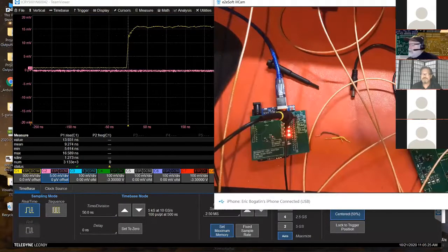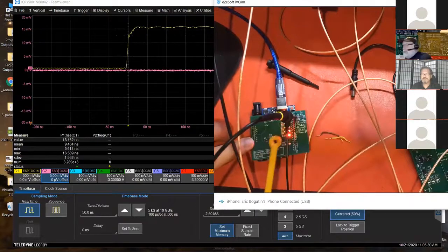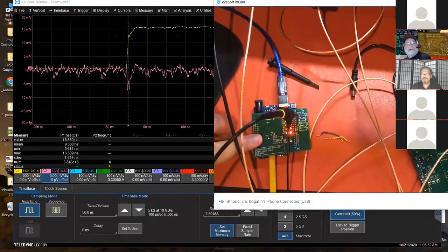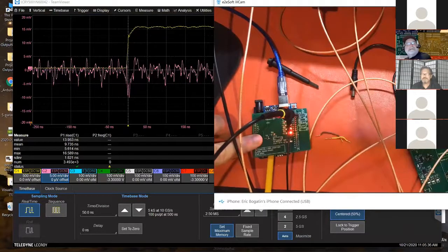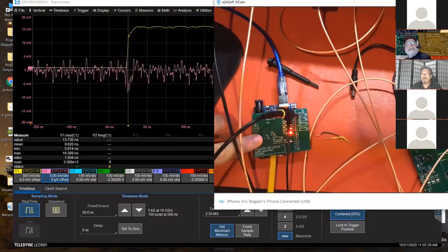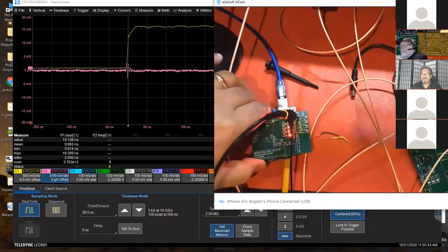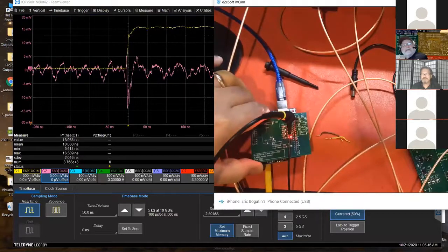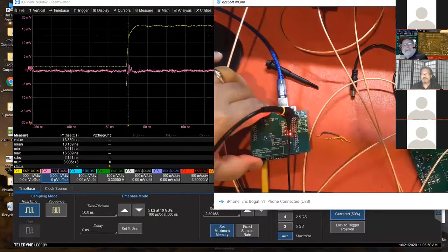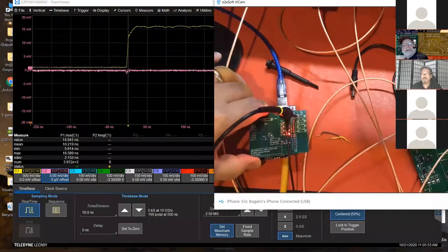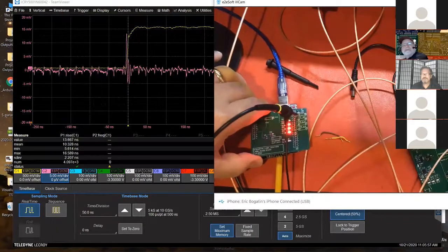But now let's look at the radiated emissions. Near field, okay, that's just about our shield, about the same. Here's the board level emissions. You know, kind of about the same. We see both the clock edge noise. We see some of the I/O. Oh my gosh, we got a lot of additional noise going on. But let's look underneath the board. So now we're underneath. And now, can you see all that near field emissions? The large area of the ground planes on the bottom of the board are radiating like a banshee in some places here. That's what's going to cause far field emissions.